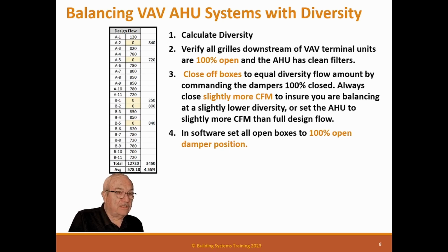And to do that is command the software to just drive the damper 100% open. It knows where that is, and it will do that. It's the safest way to do it. It's probably the fastest way, because running around setting all the room sensors takes some time. If you have a good programmer on your system, you should be able to do this with a global command. Command all boxes open. Now, you might have to do that first and then close the ones you want 100% closed later. But whatever you have to do, whether you have to do them one at a time, you need them 100% closed.